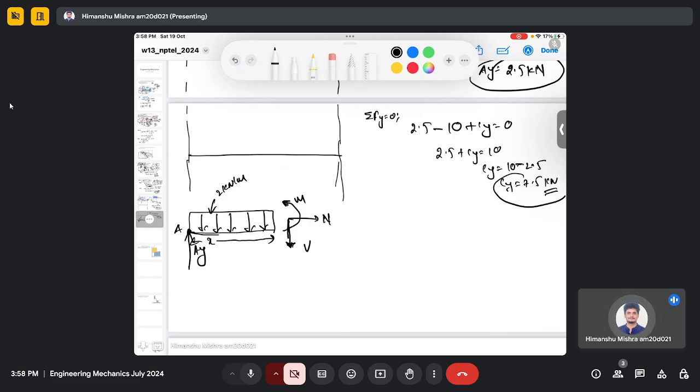Right, so now we need to do the force balance analysis in this part of the beam we have considered. The force balance is pretty easy. First we need to find the magnitude of the equivalent point load of this uniform distributed load.